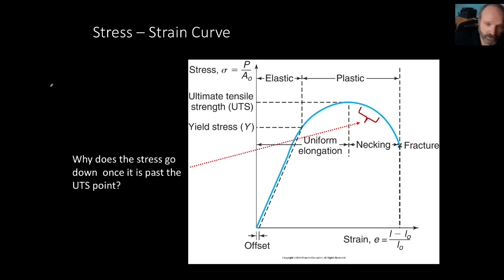So here's your stress strain curve again, and there are some definitions in here. You have an elastic region. That's where this curve is straight. So what happens is if I stress it to this point right here, I've elongated it by this much. Now if I let go, the material will snap back to its original length because you're in the elastic zone. It's elastic, it's stretchy.